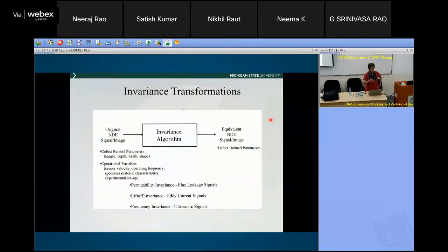Condition monitoring also does it, but usually the term monitoring is given to systems which are in a continuous mode. They ping, for example, you have a bridge, every 2 hours they send out the signal, everything is analyzed, and they will raise an alarm if something is wrong. So it's a different usage of the NDE system. Everything is NDE, you're right, no difference. But condition monitoring, or structural health monitoring, is a little bit more because it's automatically done every hour, every day, or every week, or something like that.